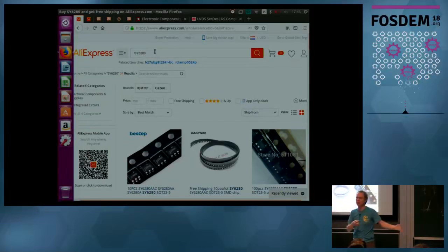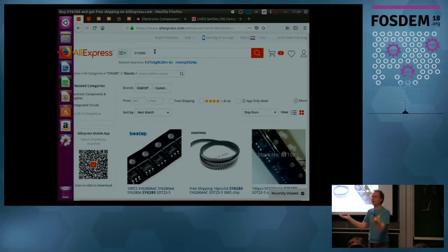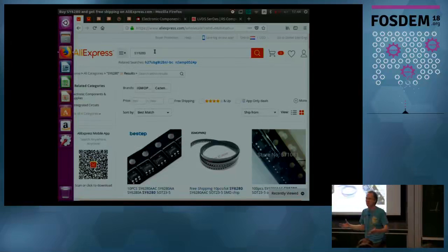You have to do the current limiting yourself. Now, in some cases, like the Silergy SY6280, you will not find the datasheet online. The only way to find out about this chip is to find somebody else's schematic which has this in. So it's a bit of hit and miss. Some stuff you will find on DigiKey or similar really easily. Some of it you will just have to find somebody who has specialists in this area and knows their parts, okay?